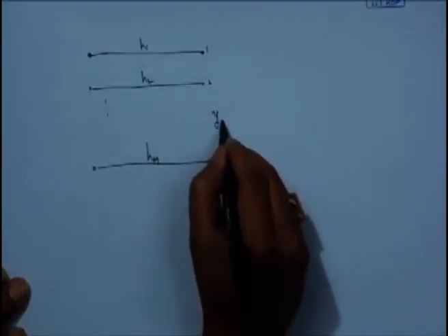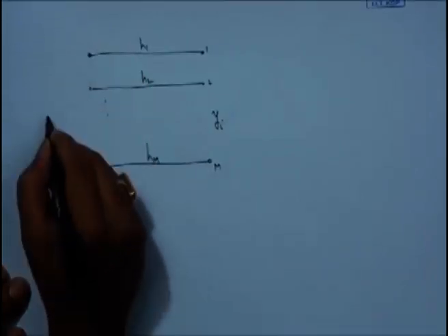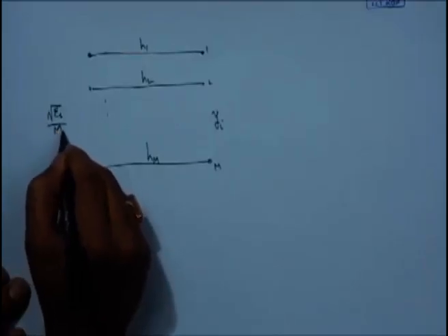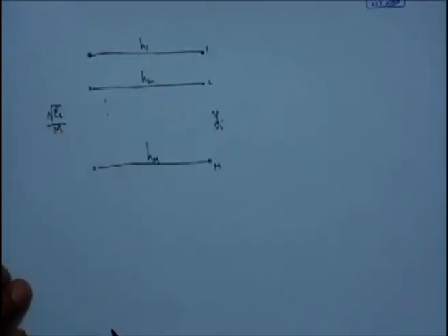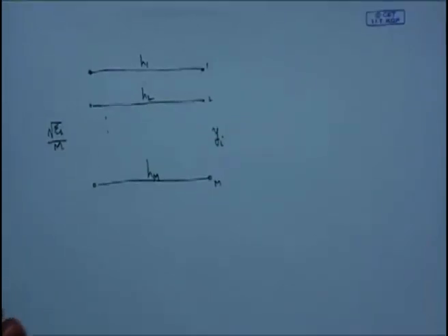So basically yi is the ith received signal, and from the transmitter we are sending root over Es upon M as the signal energy or the signal power per transmit branch. When we are doing transmit side diversity, that means you can consider time diversity, frequency diversity, or even spatial diversity. When we are doing diversity from the transmitter side, a general diversity, that is what we can consider. We have this particular thing at hand.